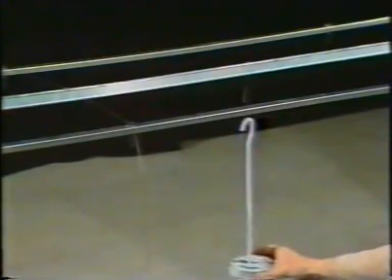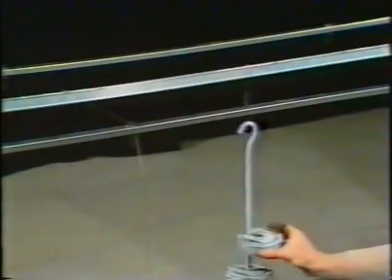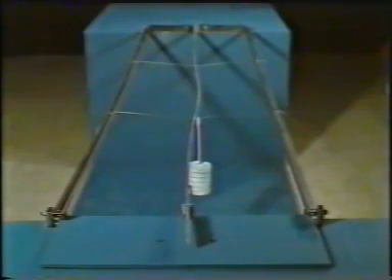Load is applied and, relative to the unbraced beam, the carrying capacity is considerably enhanced, as buckling can now only occur between braced points. On plan, the elastic horizontal distortions show that the effective length of the beam is reduced to 1/3 of its overall length. For example, the shape of the middle third is the same as the buckled shape for an unbraced, simply supported beam. This results in a corresponding increase in the critical moment.